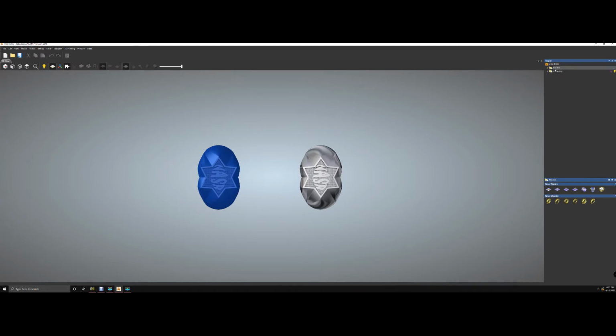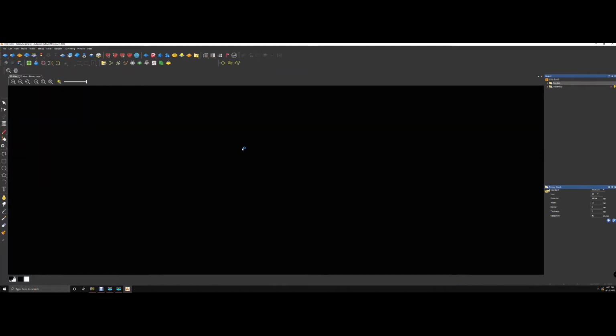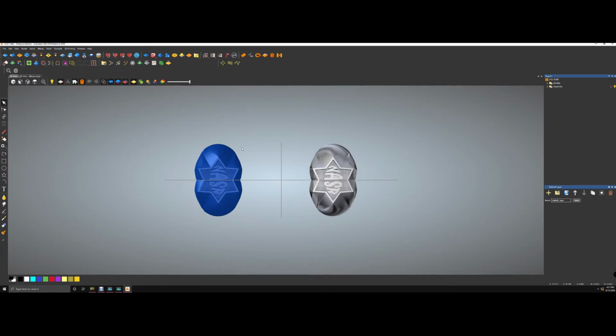So I'm just going to create a simple model. I'm going to go to the rotary axis and just right here, pick any size. It's just for the demo only. Okay, so let's get size 10. And I'm going to show you how to create the actual rotary axis toolpath.